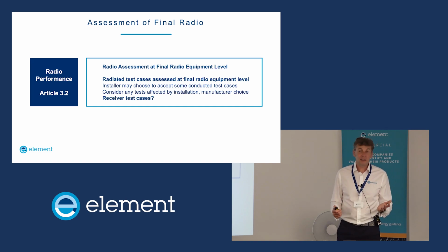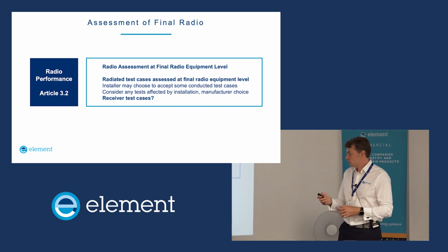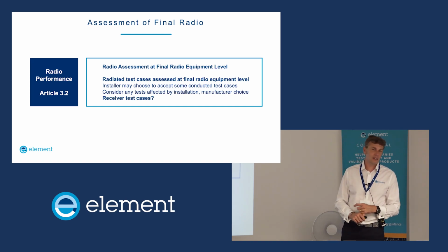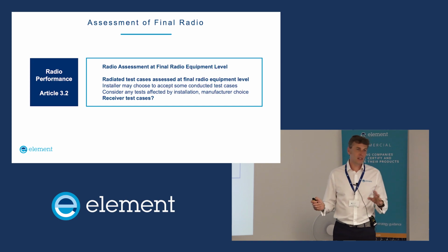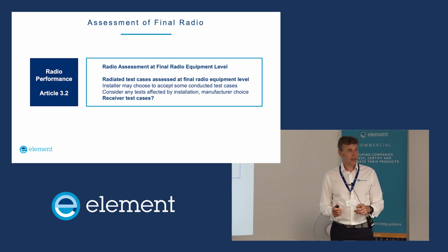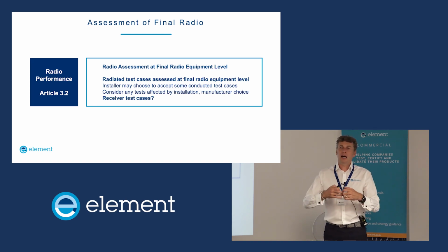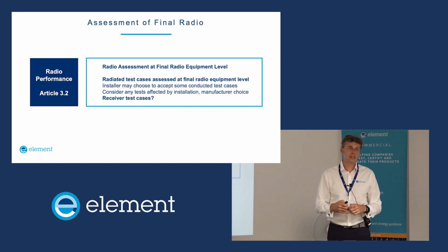And that seems fine. I do end up with some funny conversations with people where they'll go, oh, well, the radiated spurious emissions test will only ever be better than it was on the module. And I'll go, okay, why is that then? And they go, well, the module was tested open. And so as soon as you put a module in something else, it's bound to provide shielding. So the emissions coming off the module will be better.